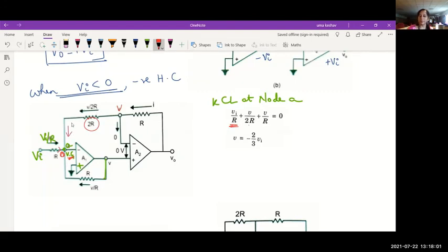It is also entering. And what is the current in this? The third branch here is this resistor. The voltage here is also V. If this voltage is at V, because of the principle of virtual short, this should also be at V. It is understood. So V minus 0 by R again, which will be V by R. I hope you are following this.